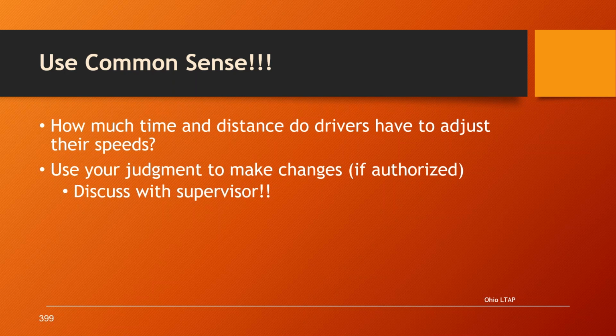this isn't 1960 anymore. I guess they tell me it's 2021 now. So we have a lot of technology at our fingertips and it's free. So why not take advantage of it? One of the things you can do is use Google Maps, right? Google Maps is a very good tool for helping you to quickly come up with a work zone design before you leave the garage. That way you know how you're going to set up traffic. You can decide on a typical application and you can load up your work truck with the proper signs, for instance, and all the temporary traffic control devices you need that day.